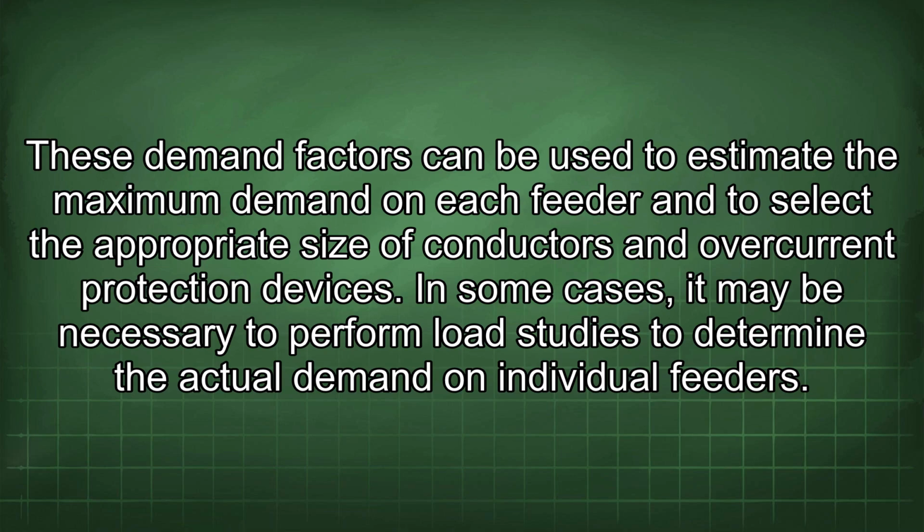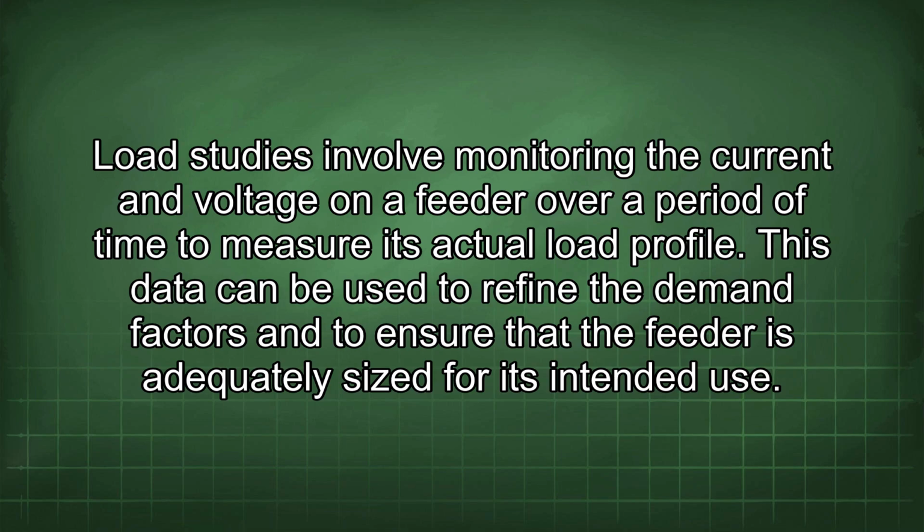These demand factors can be used to estimate the maximum demand on each feeder and to select the appropriate size of conductors and overcurrent protection devices. In some cases, it may be necessary to perform load studies to determine the actual demand on individual feeders. Load studies involve monitoring the current and voltage on a feeder over a period of time to measure its actual load profile. This data can be used to refine the demand factors and to ensure that the feeder is adequately sized for its intended use.